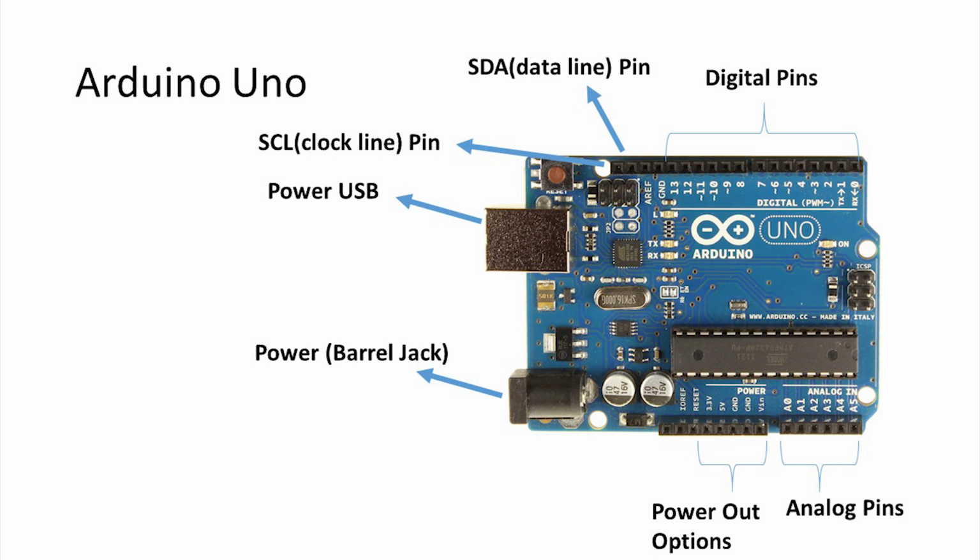The analog pins connect to sensors that use light or audio. As for the digital pins, they connect to sensors that have binary outputs, either low or high. We will be using these pins to communicate with the Bluetooth module. The SCL and SDA pins help with communicating with sensors that need to take data at specific time intervals. We will use these to communicate with the current sensor.